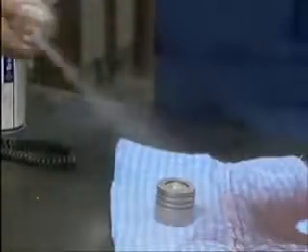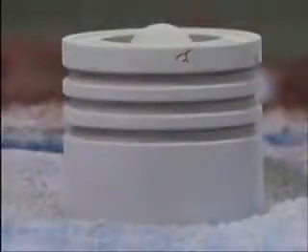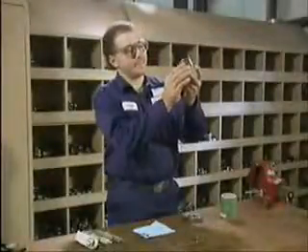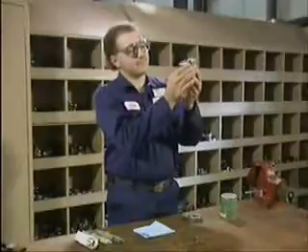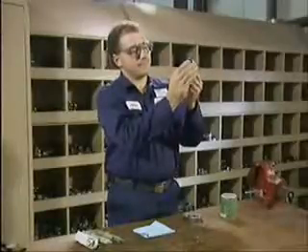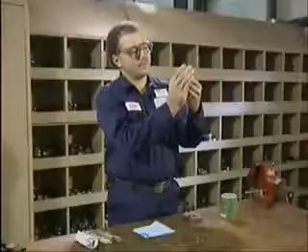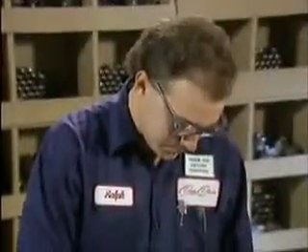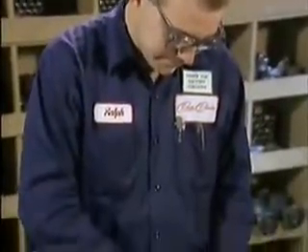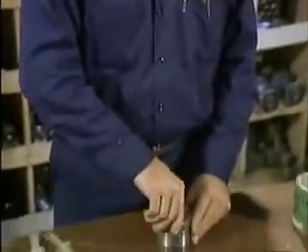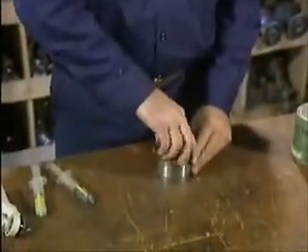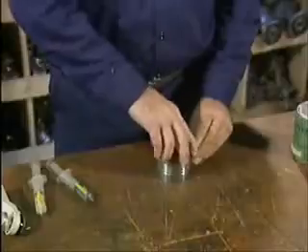Now, coat the surface of the disc with a developer, which is a substance that draws the dye back out of the cracks. Any cracks or flaws that are present show up in the developer. Also check the disc for steam cutting. If steam cutting is severe enough to allow leakage, you'll have to replace the disc. But if the damage is relatively minor, you can often restore the surfaces by lapping them. You'll need to follow the appropriate lapping method for the shape of the disc.